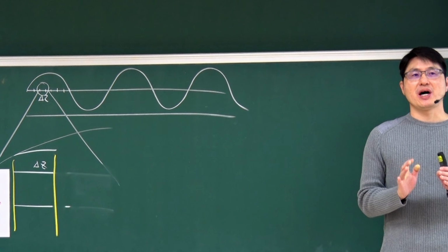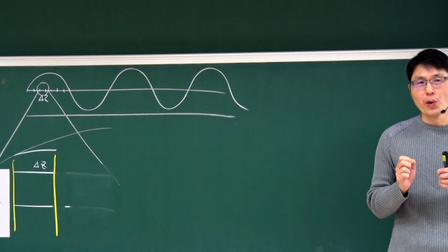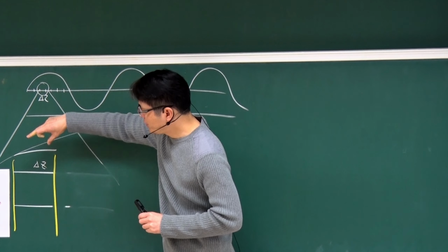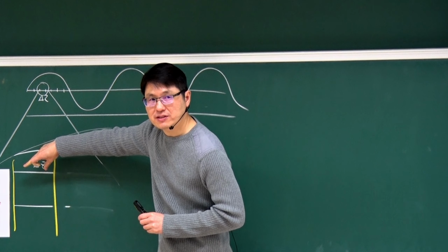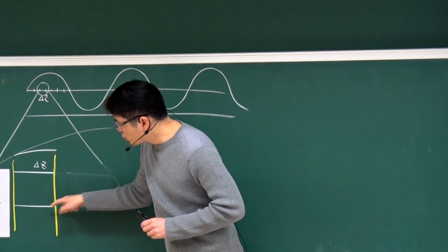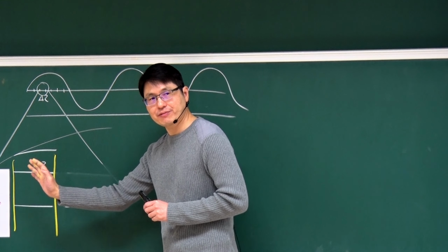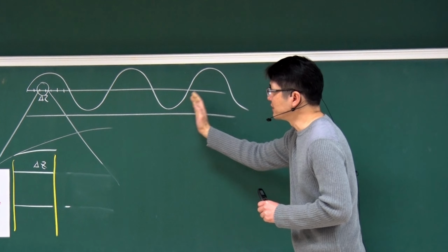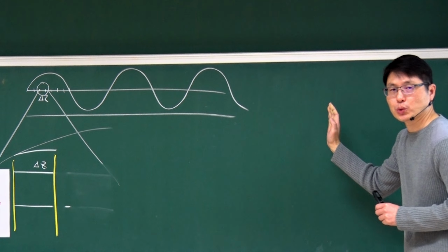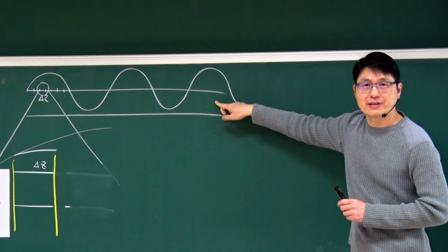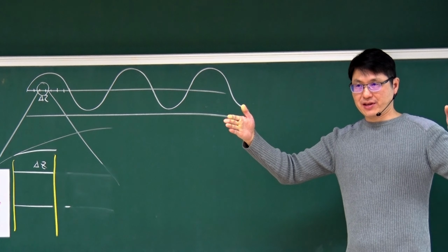So now our job is to find the equivalent circuitry model for that very short transmission line segment. If we can analyze this short segment, all we have to do is connect a lot of the same identical short segments to recover the full length of the transmission line.